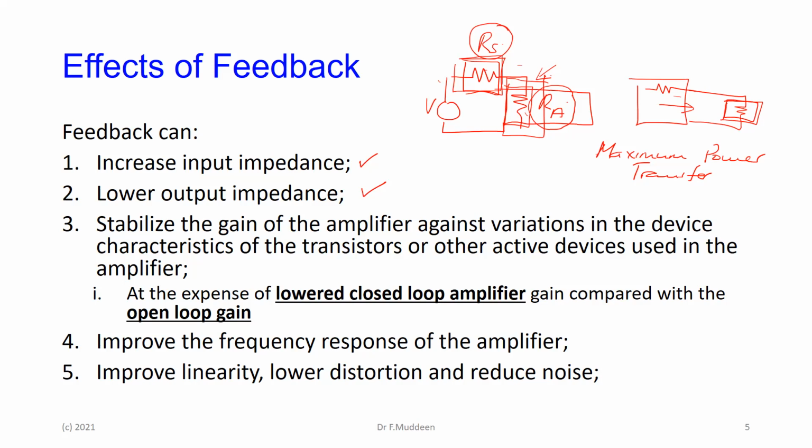Of course, when the device works, it gets warm, so those characteristics change. And then current passing through resistors and other passive components causes them to heat up, and their values change because they're being asked to dissipate energy. Once something is working electronically, it means current has to pass through, and once current passes through any electronic device except a superconductor where the resistance is zero, it will be dissipating heat, and therefore its value is going to change. So what you're trying to do is have some way of stabilizing the gain of the amplifier against the variation in all these things.